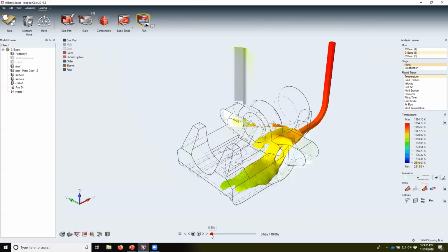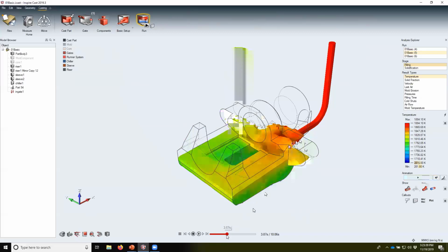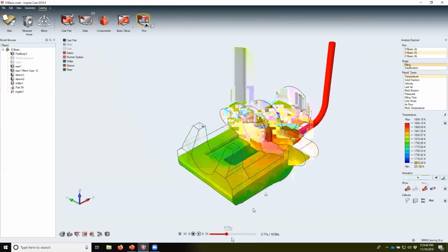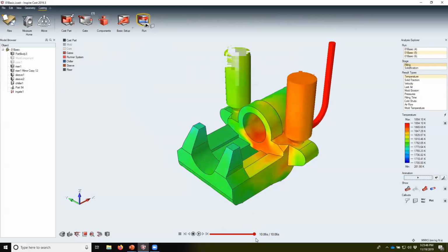So it flows over there, and I'm expecting to see a bit of erosion in the bottom of my mold now, but hopefully not as bad as what we saw on the sides there. A more natural place to fill it anyway. Then it fills all the way up to the top. It fills those risers all the way up.